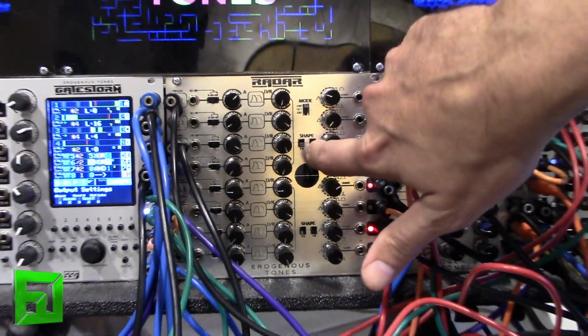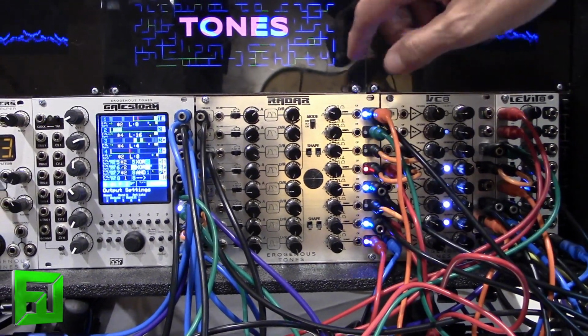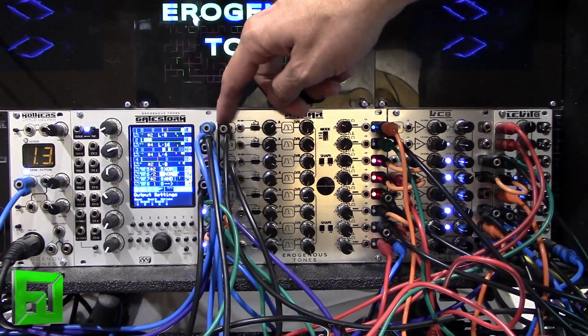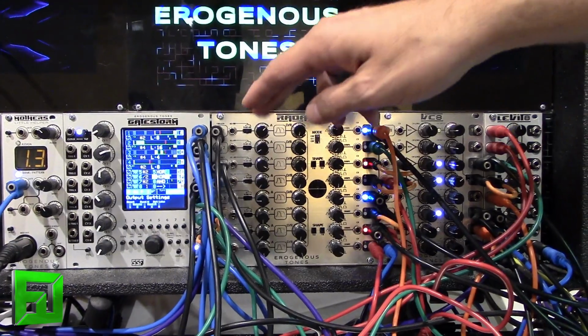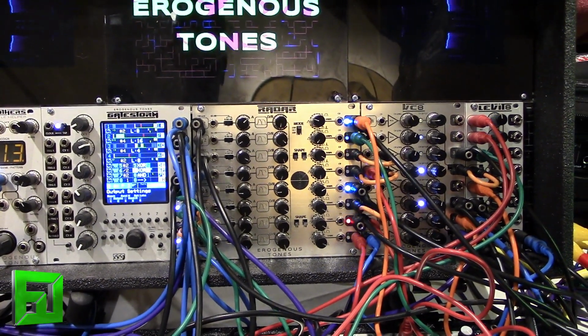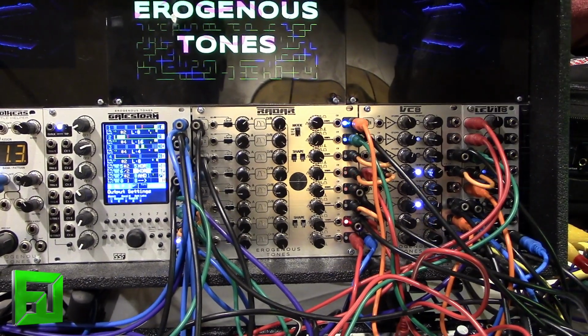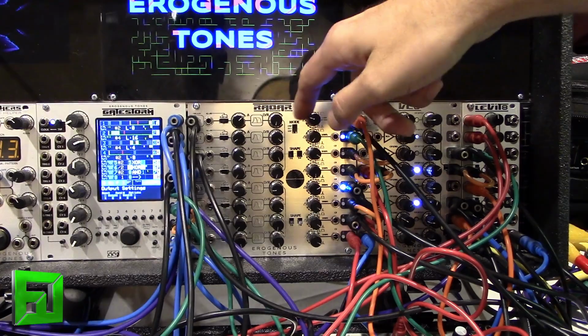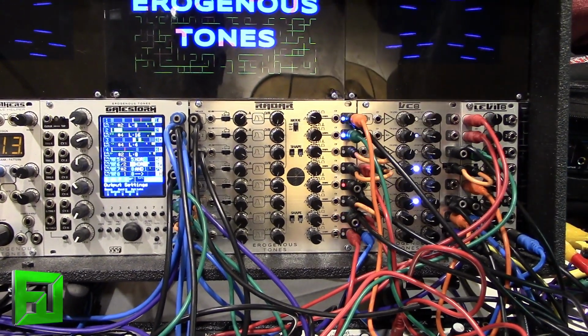Then the other thing it does, the second button, is you can do analog modeling or digital. In analog modeling, if you send a trigger reset and you're still in the attack phase, it's just going to keep rising. And when you're in the release phase and you send it, it will just start accumulating again from that point. So it works just like Maths works that way. It's completely analog. In digital mode, it's kind of like the Doepfer where it resets to 0.